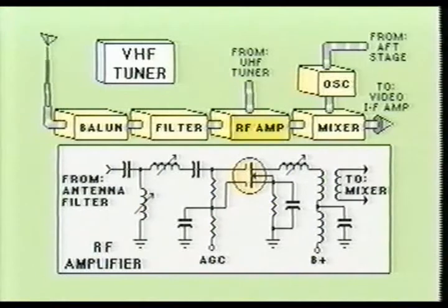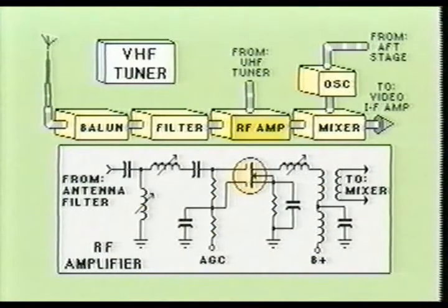As you saw earlier, the radio frequency spectrum covers a very broad frequency range. Therefore, the RF amplifier stage will only amplify a narrow portion of this entire spectrum. Since the RF amplifier can only amplify a small portion of the entire spectrum, you will typically find a tuned circuit at both the input and output of the amplifier section. The tuned circuits will be adjusted to a limited bandwidth for the amplifier stage.